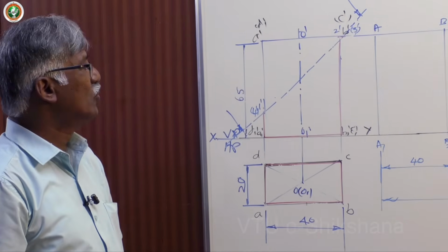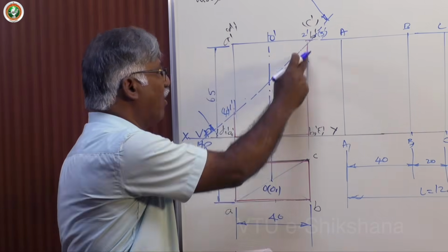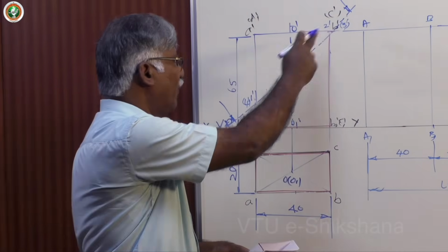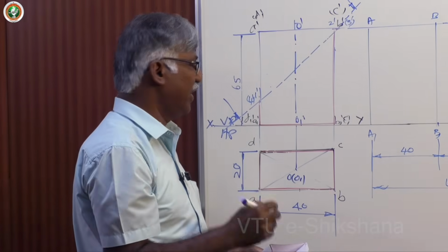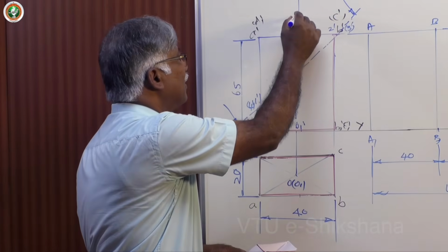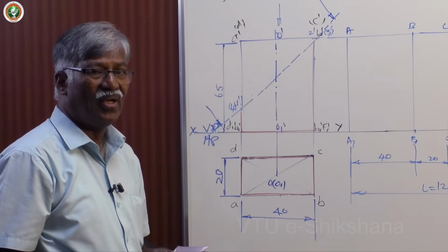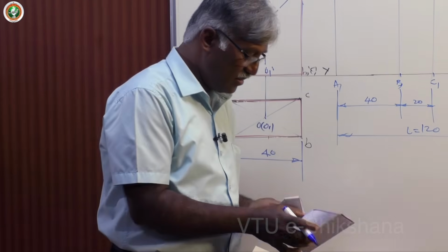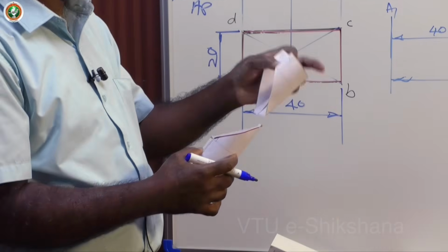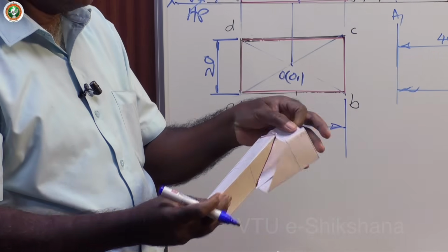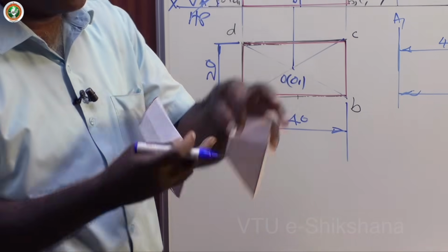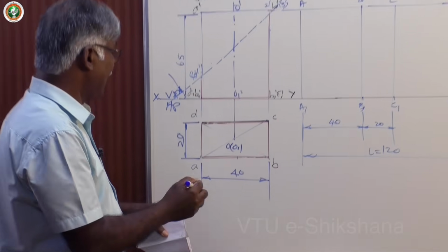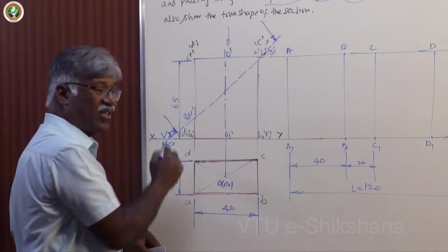Okay. So this portion is to be made dark. You retain this as a light line. Initially you make it light, and then after drawing the section plane, you dark this portion. Now, you look at this in this direction. What is the top view? You don't have the top face. Basically, assume that this particular model I have taken at the mid point of the axis and cut it. Then this surface is not available. So naturally you will get this particular section visible.